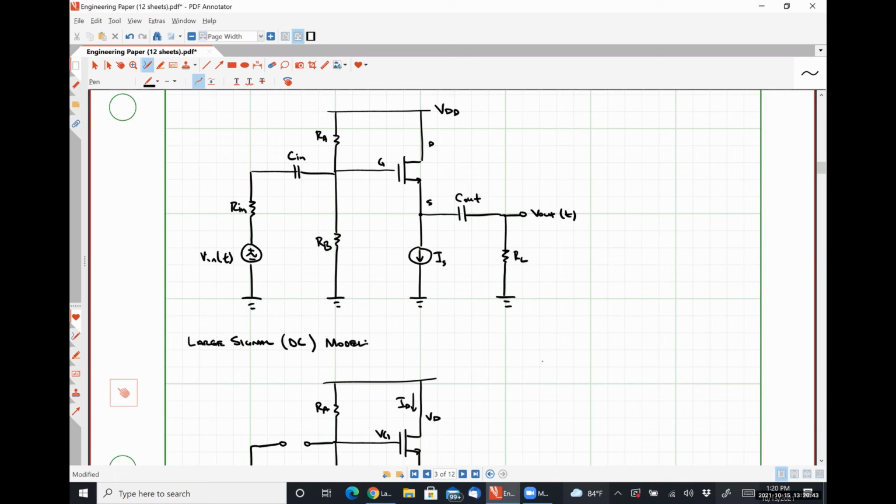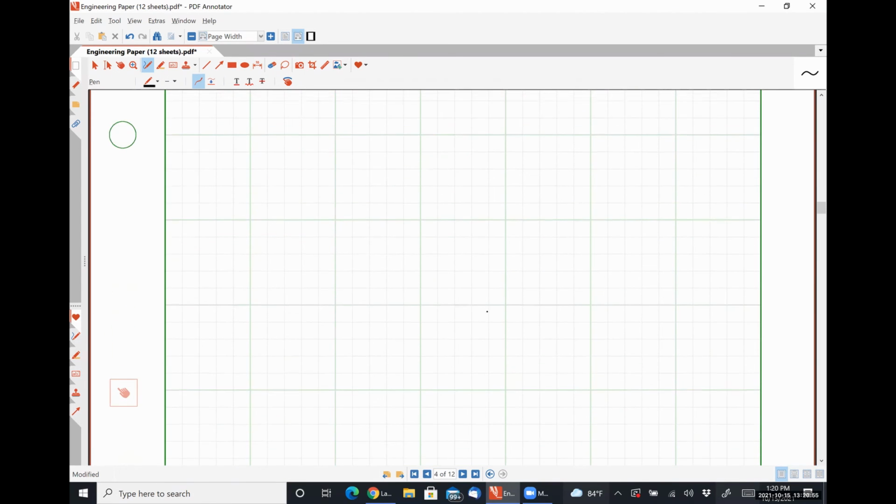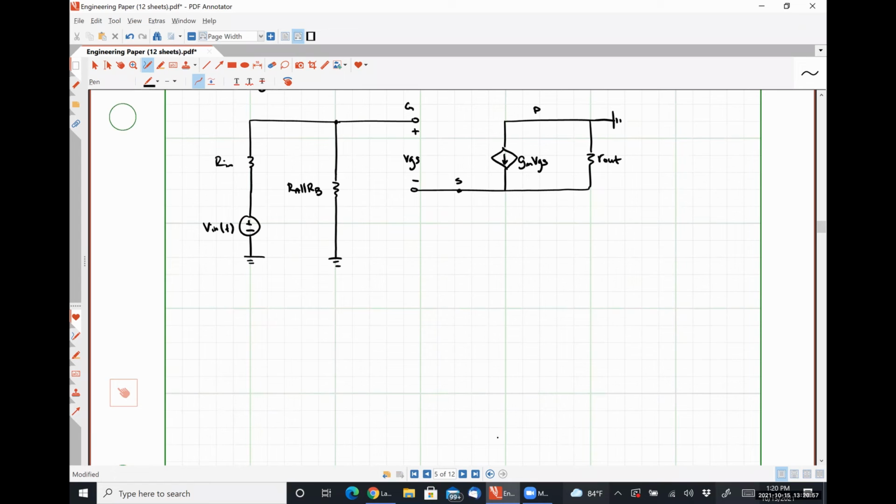What happens to the current source? Open circuit. We turn the current source off by replacing it with an open circuit. Absolutely right. So here, this is where my resistor RL should go, and my output voltage V out is the voltage drop over this resistor RL.